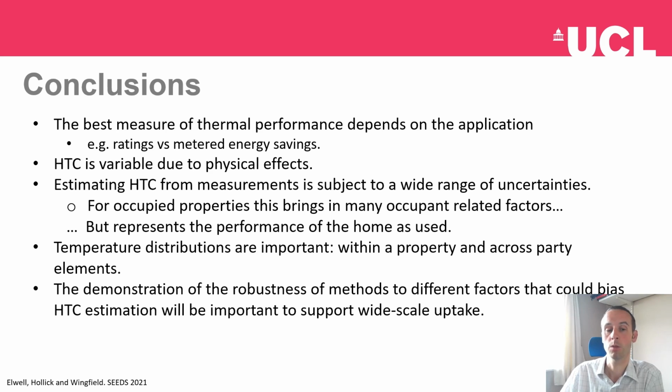However, we need to think about what we're really trying to achieve from this, and whether we are interested in the occupied state or the unoccupied state, and how transferable we expect the HTC rating measurement to be for different occupants. Using a simple example of a basic model, we can see how important temperature estimation is, both within a property and across the party walls.